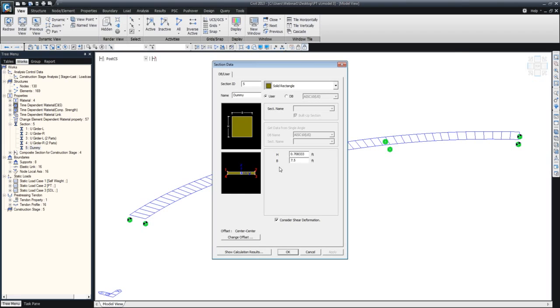So engineers usually try to monitor the bending moment distribution between the girders by reducing the stiffness, and when they come to a point that the bending moment in an individual girder is not reducing after a certain point, that means it is not being shared any longer with the adjacent girders, they come to this limit on the width. So this is the standard practice.